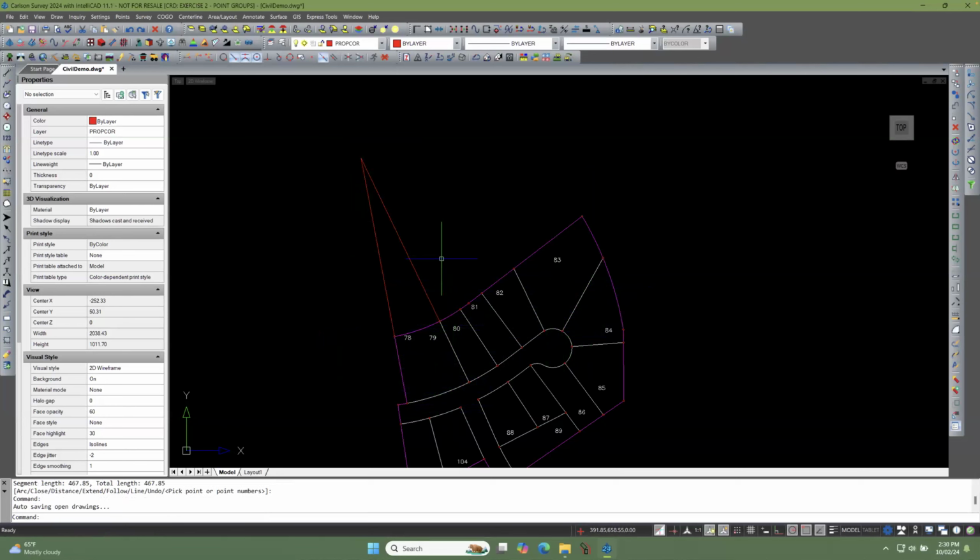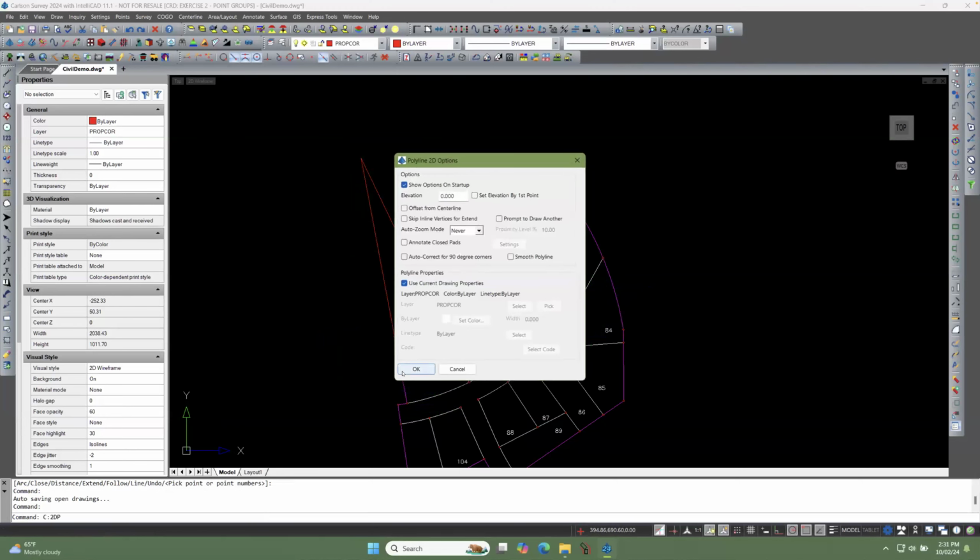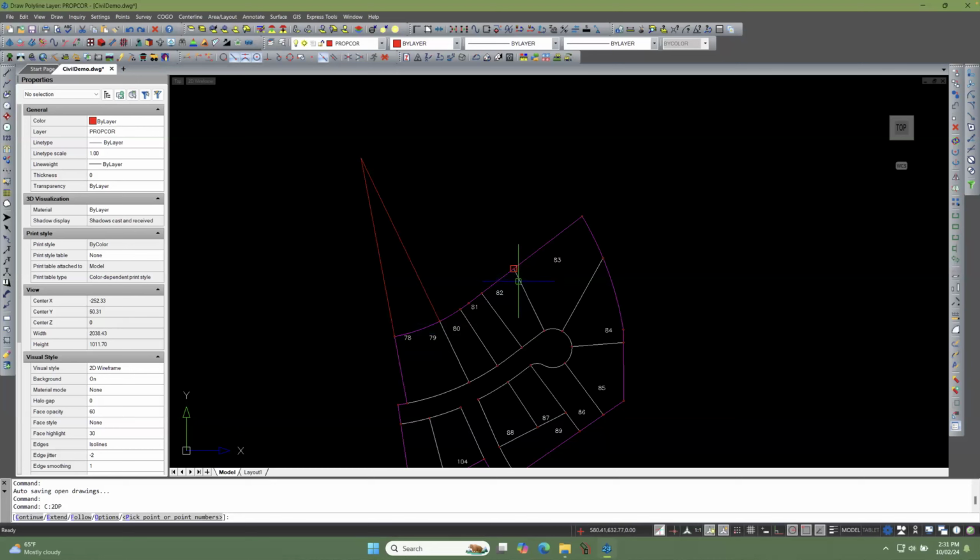Okay, now, notice when I'm doing this, that when I hover the mouse, see how I get the end point, midpoint, I get all these different things that pop up. Those are called running O snaps or running entity snaps or E snaps. And here's where they're set. I'm going to press escape to end that command.